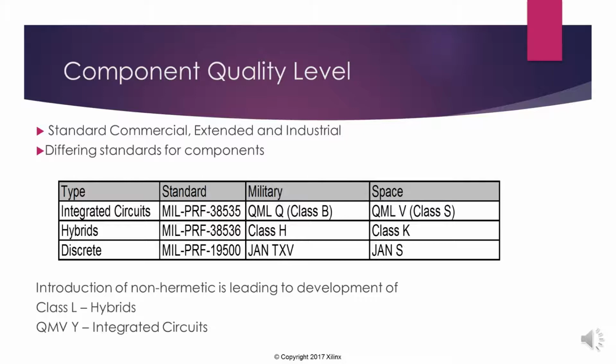They're really good these days. I can't remember the last time I had a standard component fail on me, really, as long as you've taken suitable care and practice with it. You can buy them with extended temperature ranges, or with an industrial temperature range. If you're in a really demanding application, then you can perhaps consider buying a military or a space grade component, one that aligns with QMLQ or QML or QMLV.